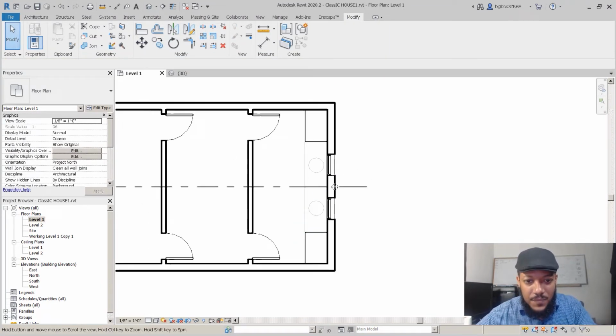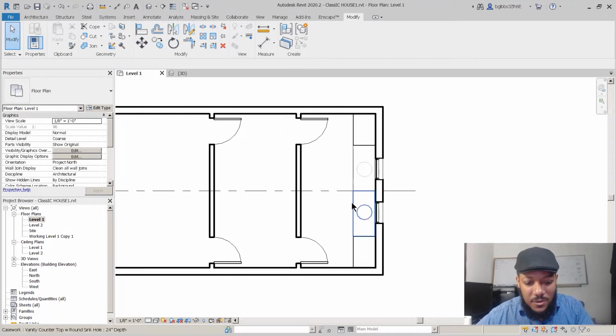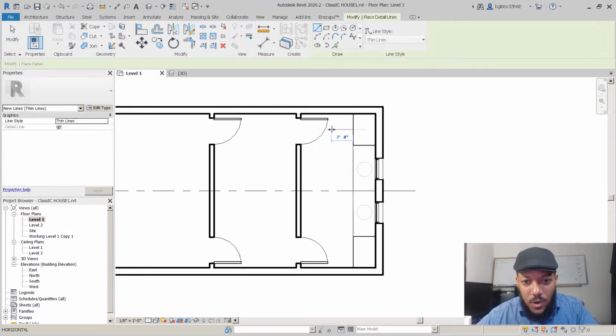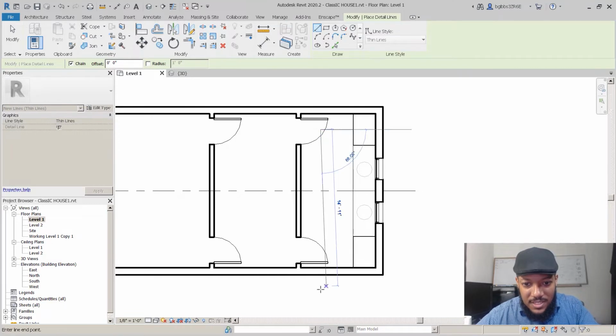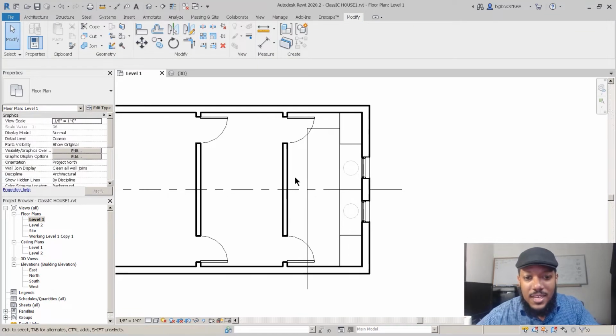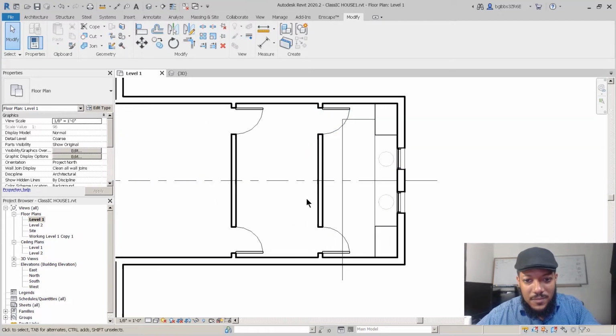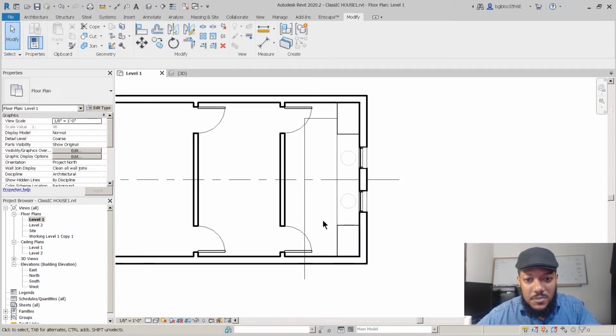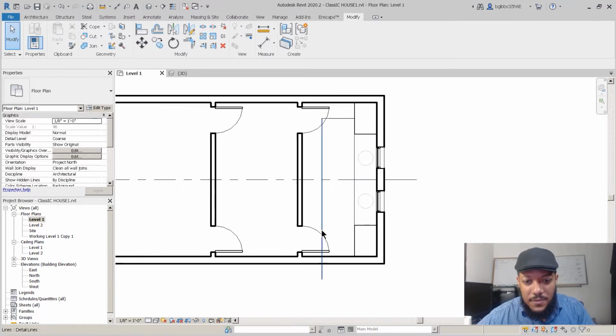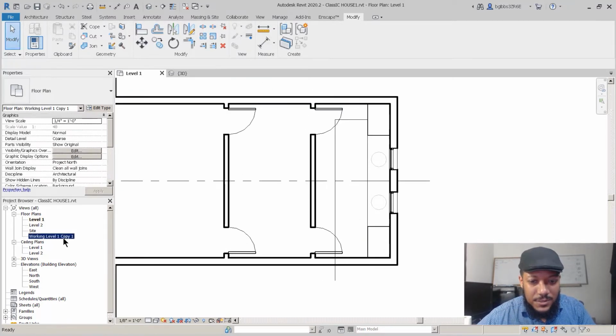And one other thing is now we're looking at our bathroom, and if we look at clearance for walking and such, we want like 3 feet. We see that we're a little bit short. So our bathroom, we probably want to have it at a bathtub, and we might even want to put the bathtub on this side of the space. So using the information we have here, we have to figure out some design moves. So we'll go back to our working level.